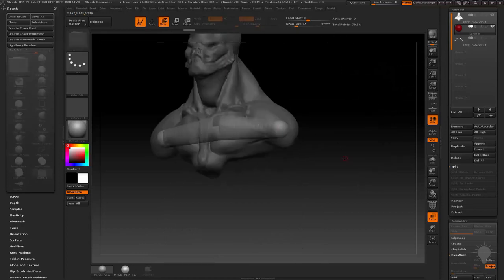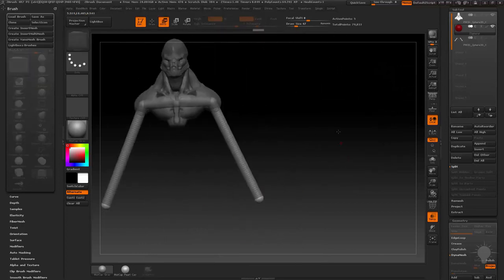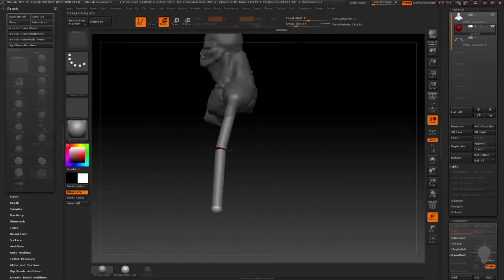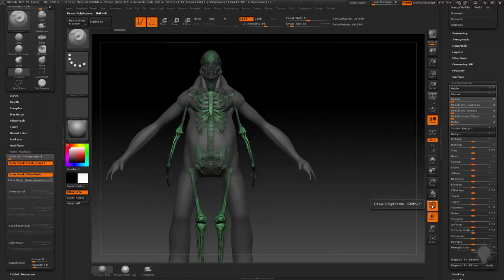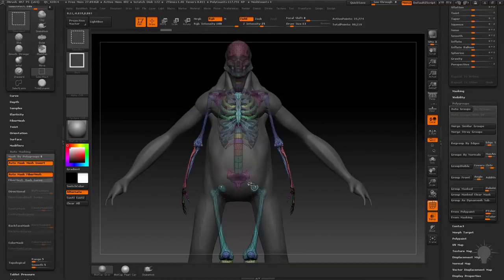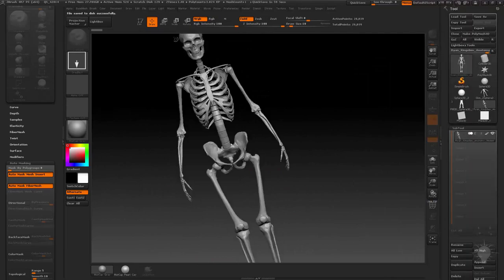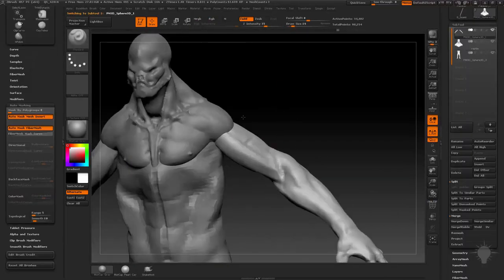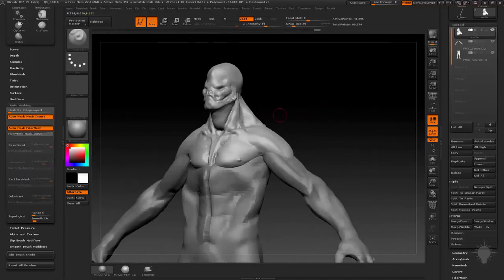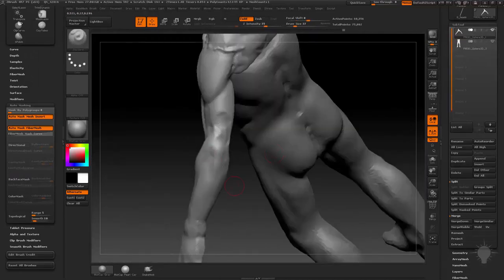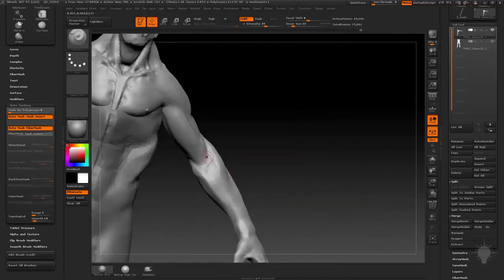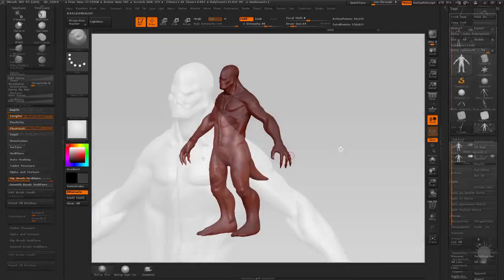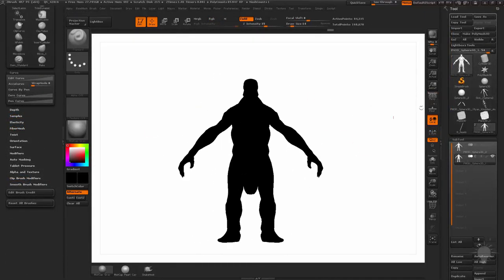From the simple bust blockout, we'll move on to body creation, covering a number of techniques. And before we get too far, I'll go over a few proportional techniques to make sure our initial landmarks are correct. This will include bringing in the skeleton found in the ZBrush lightbox, making a head unit plane to check your proportions, as well as utilizing the transposed line preferences to mark head units for easy proportion checking. We'll also do a section on evaluating silhouette in ZBrush, and utilizing basic material and light setups to check your work as you go.